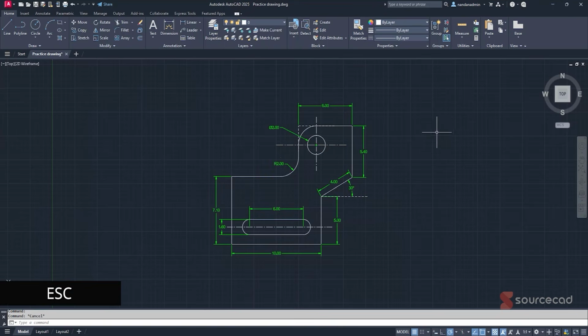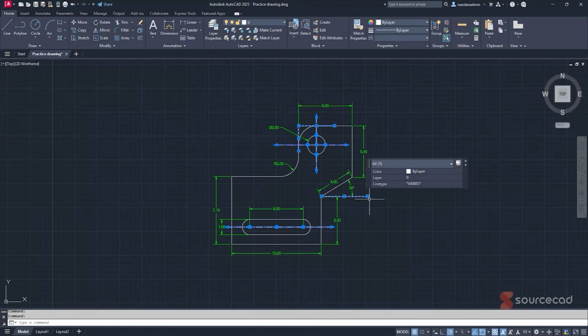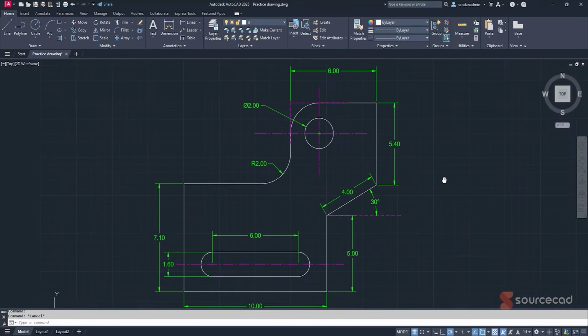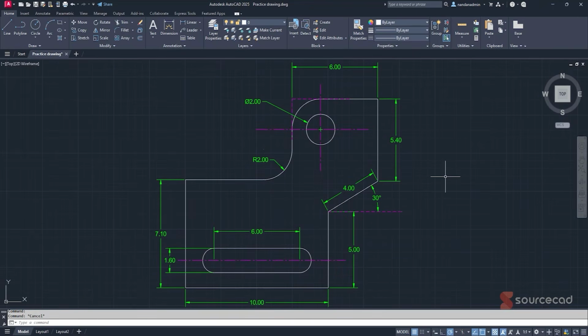Now press escape and immediately you'll notice that it will take the properties of that new layer. Now these things are construction geometry. So let's select these things, the construction geometries that we have in the drawing. All right. And let's put it on the construction layer. And it took the properties of the construction layer. As simple as that. Not just that, we'll add even more properties. Now remember we added transparency here for the construction geometry. Well, we'll do that again, but this time without using properties.